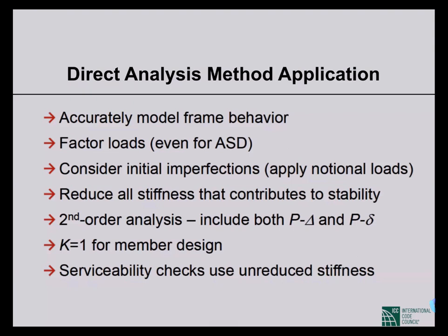Second important issue is that we have to factor the loads. For LRFD, this is not a problem. We always factor with overload factors.